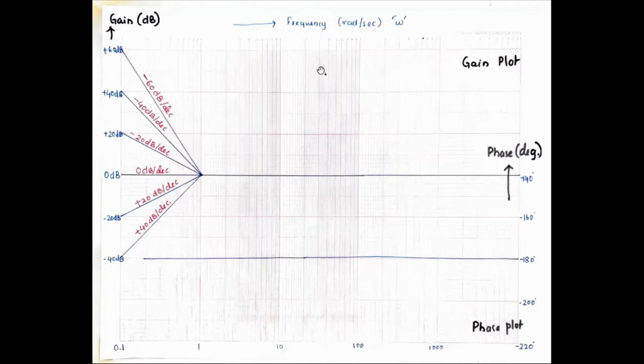So with this, we will go to the first, gain plot. So gain plot is nothing but drawing the gain of the open loop transfer function. We have already seen how to write the expression for gain in the Nyquist plot. So that is gain of G(s)H(s), or gain of G(j omega)H(j omega), equal to square root of something something. Okay. So that is nothing but the gain expression. And for each frequency, we will plot the gain here. So we'll see next.